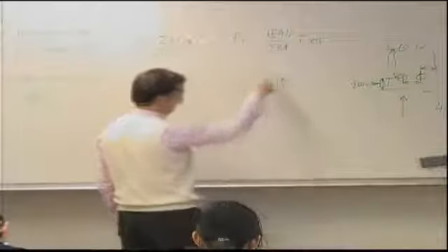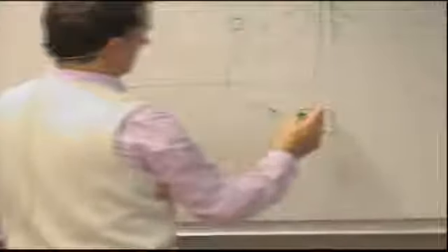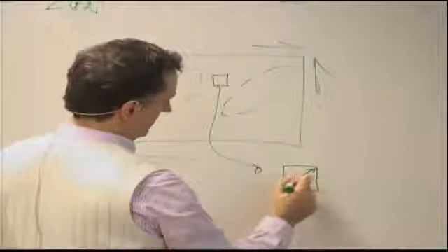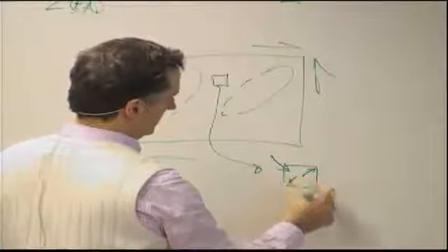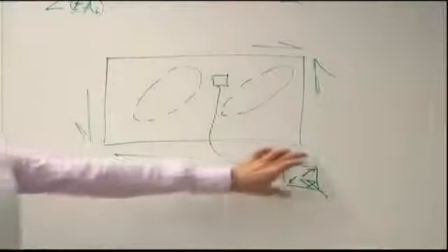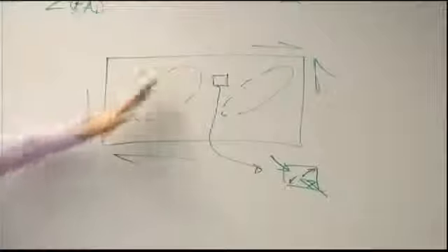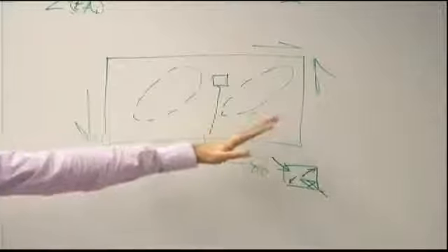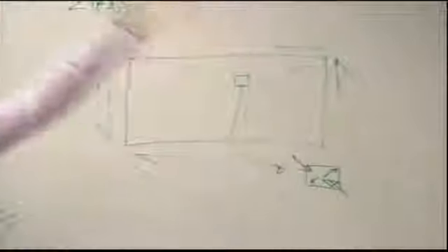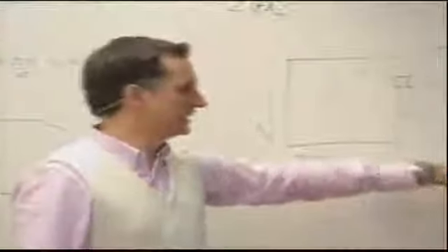As we said before, the pure shear becomes a tension in this direction and compression in that direction. So if every single square here has tension in that direction aligned more or less with the diagonal, in fact it's aligned with these half waves, and compression perpendicular to that direction, as I increase the shear load from 0 and I keep on going past the buckling load, what happens to these little squares?